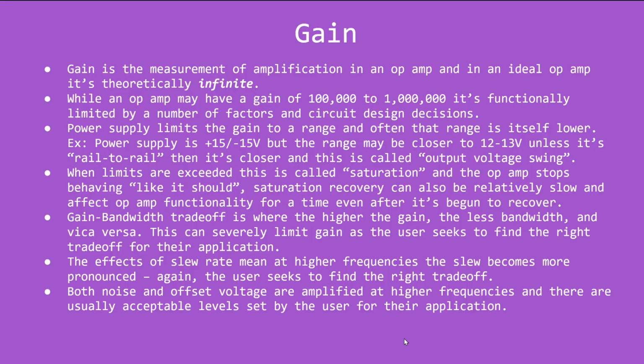If these limits are exceeded, you have a thing called saturation, and the op amp basically stops behaving like it should. Keep in mind that saturation recovery is a factor, and it actually may be relatively slow compared to other operations.